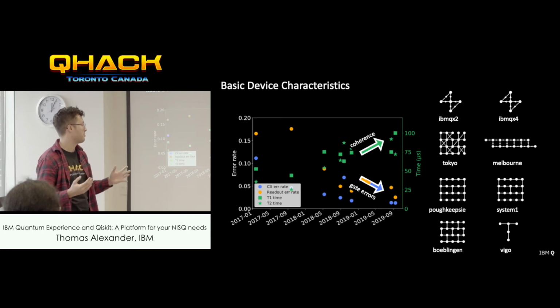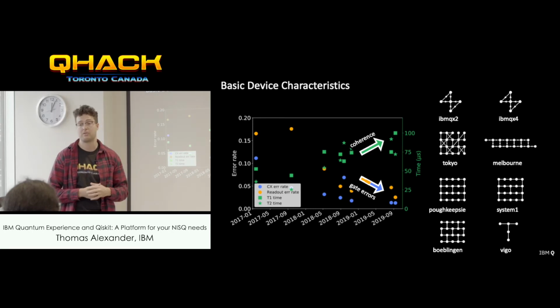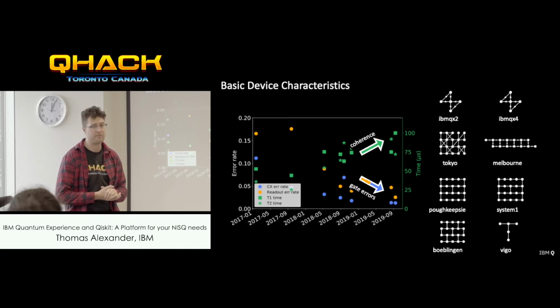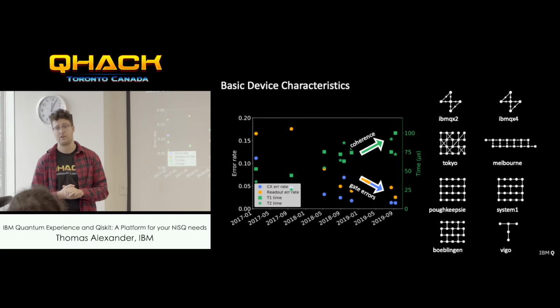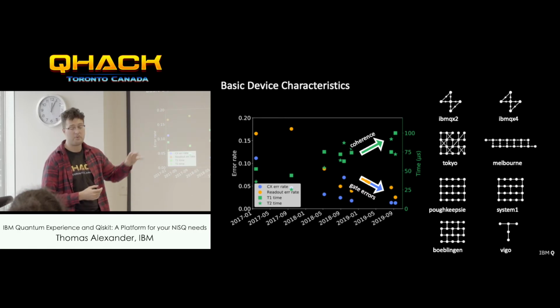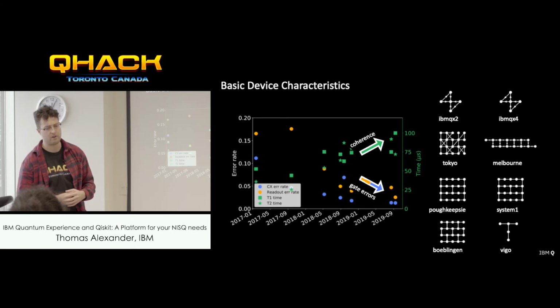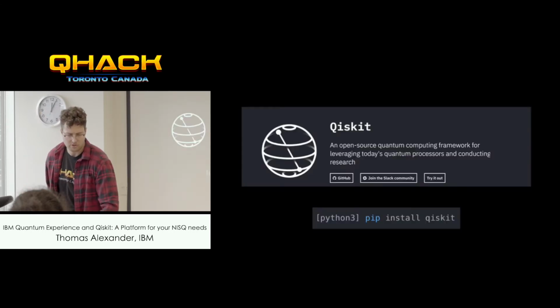I'm actually very impressed with the hardware progress we've been able to make with superconducting qubits. I think we showed a T1 time of around 500 microseconds earlier this year for a single qubit device, which, quite frankly, I was blown away that we were able to achieve. And we've also been exploring different topologies and different generations of our internal hardware systems along the way.